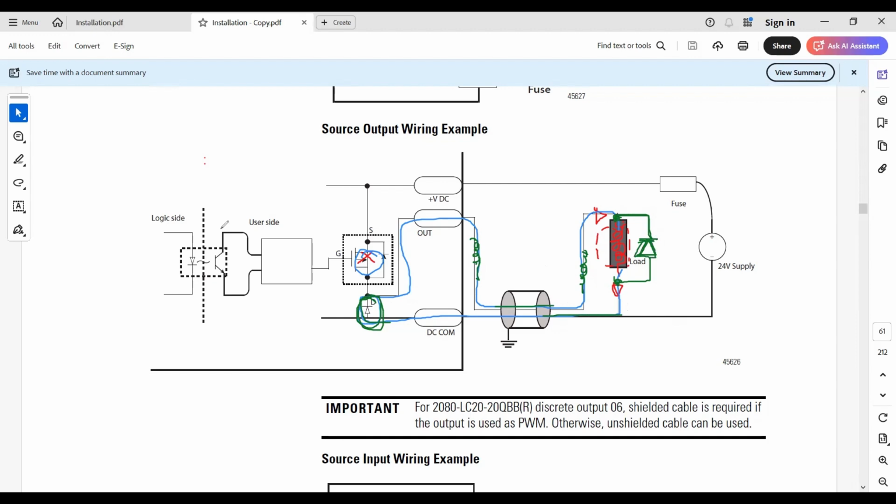Now, even if you have resistive loads, a pure resistive load having long wires might add additional inductance. So that also creates a magnetic field, and it also finds a path to return the current that is supported through this diode.